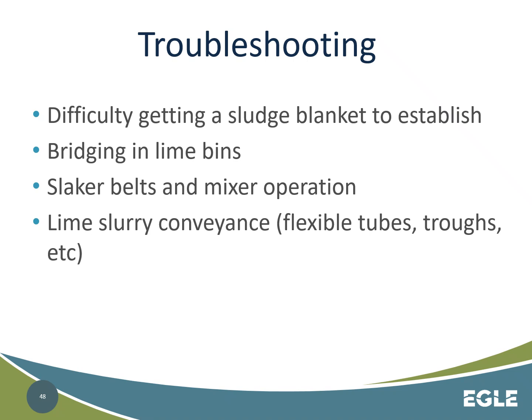Another issue can be bridging in the lime storage bins. Moisture gets into the storage bins, causing the lime to stick together and stick to the sides of the bins, not allowing smooth flow of lime out of the silo. This can be a messy and dangerous problem.